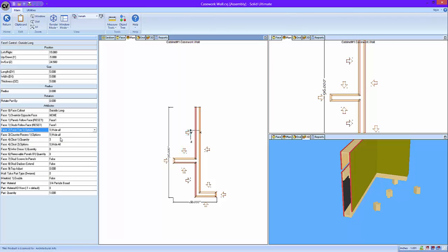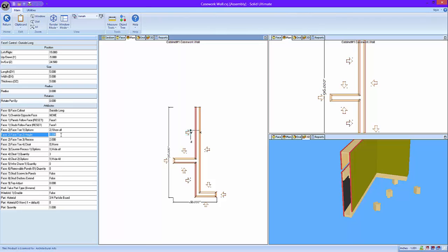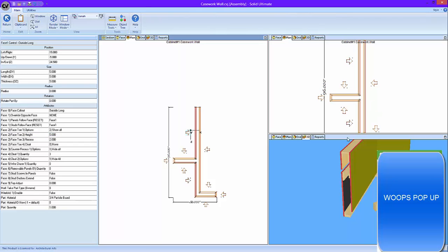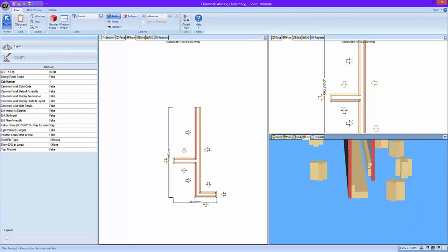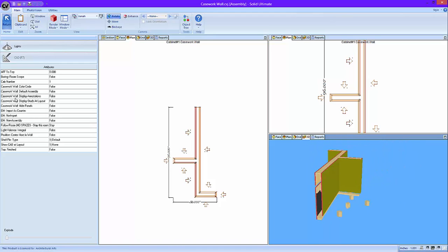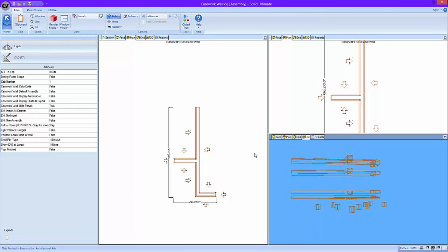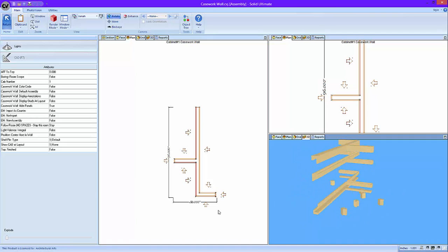We have this face toe option. We'll set that. Tell it I want maybe a 5-inch tall toe. Which you'll see pushed the cleats up. And since they're all following this one, let me go ahead and hide my panels. Since they're all following this face, it pushed them all up all the way around, except on the inside, which is exactly what we want.